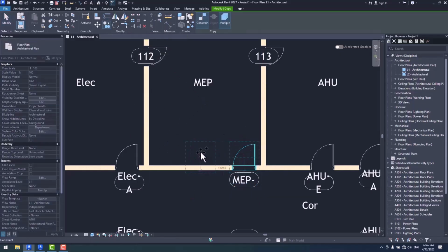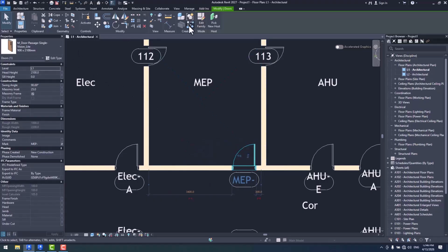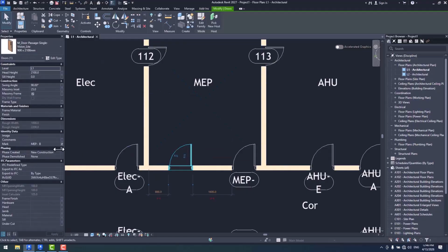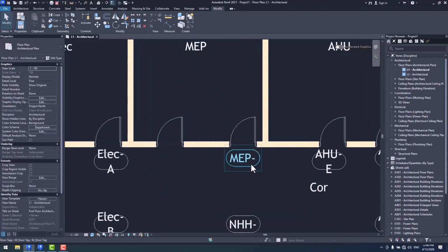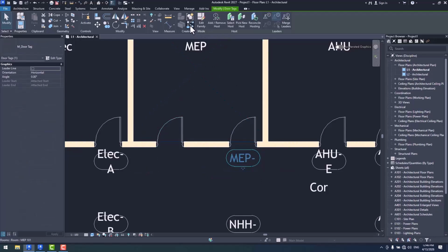I'm going to go ahead and copy this door. Or you know what? We can even set up a new door here. See, the mark is empty, but when we set the door down, the mark would immediately be specified. Guys, as I said, there's a specific rule or principle that all of our new objects are following. And by the way, guys, the parameter is important here, the mark, not the tag.